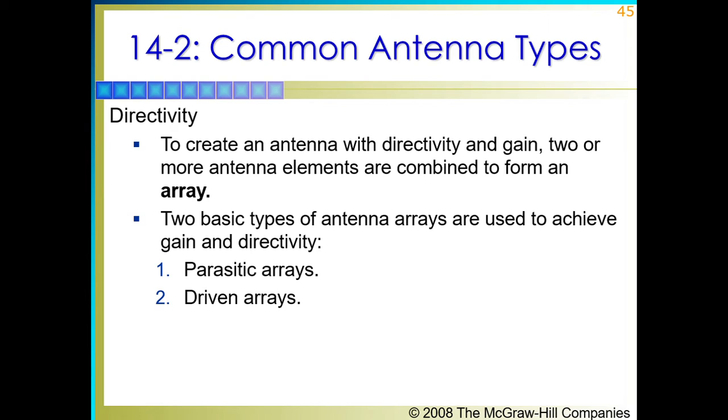An antenna array is a set of individual antennas used for transmitting and receiving radio waves, connected together in such a way that their individual currents are in a specified amplitude and phase relationship. The interactions of the different phases enhance the signal in one desired direction at the expense of other directions. This allows the array to act as a single antenna, generally with improved directional characteristics compared to those that would be obtained from the individual elements.